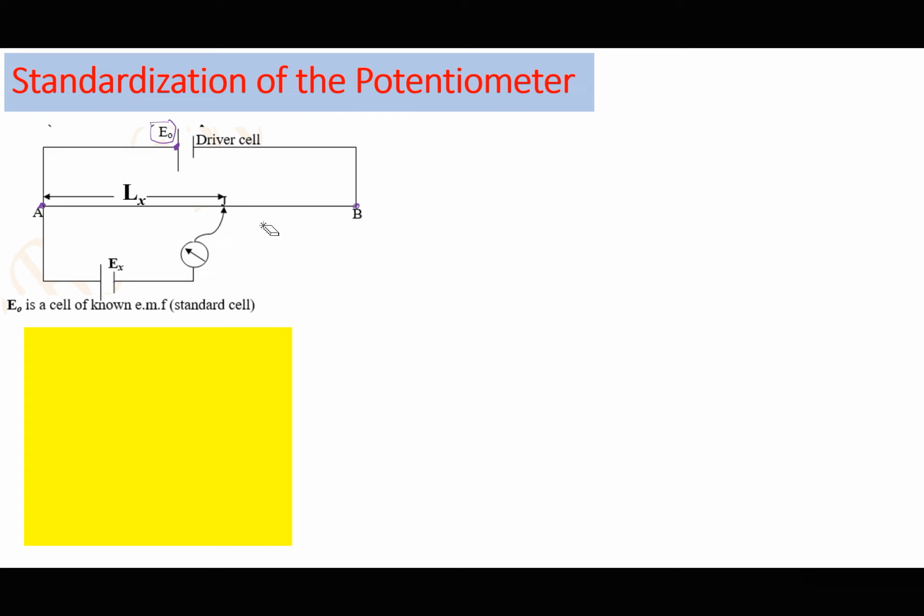that if you don't connect the potentiometer in this kind of orientation, where the positives are linked to the same common point and the negatives are linked to the same common point, you will never get a balance point.